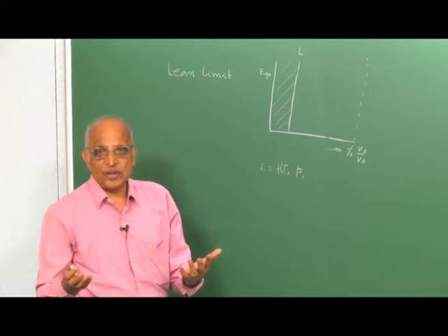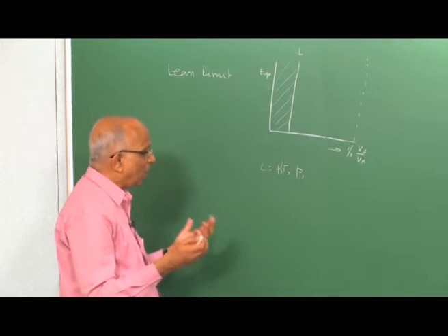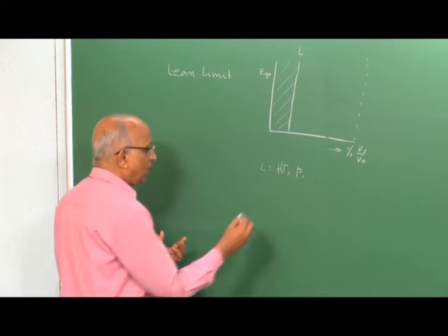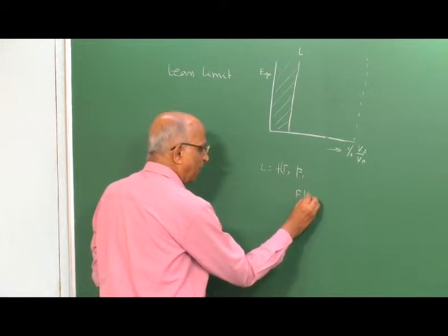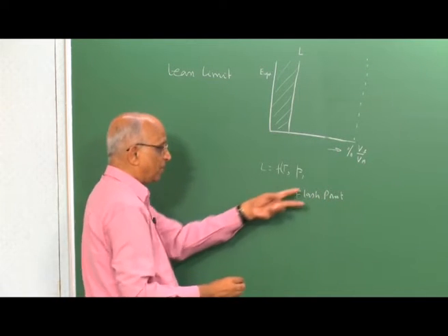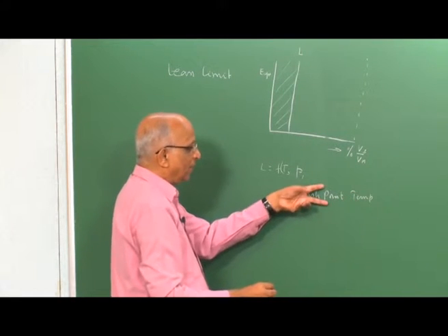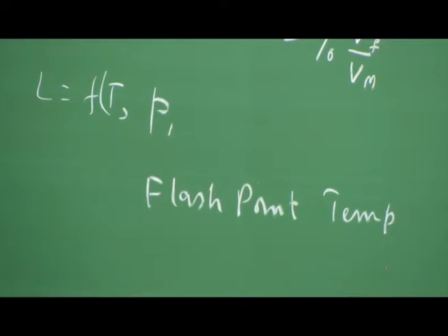We also went one step further and looked at volatile liquids or volatile fuels and talked in terms of the flash point, at which we said that at the flash point temperature the amount of vapor generated from the volatile liquid is such that a mixture which is ignitable can be formed.